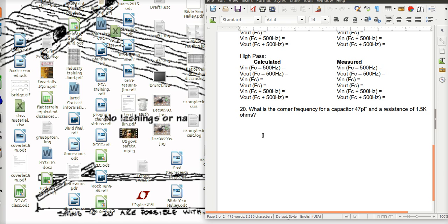These are simple filters. They have one pole, or one zero, and that's very technical talk. There are more complex filters, but if you understand the basics of high and low pass filters, then you've got a good groundwork for filters going forward as you see them later on.